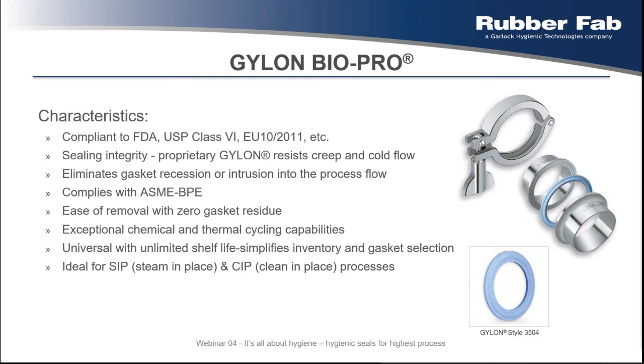The fillers won't change that in this case, and it performs exceptionally well with steam. Big pharmaceutical manufacturers have this gasket not only in their applications but also in their own testing facilities with continuous steam exposure up to 5 years without any physical damage of the gasket.